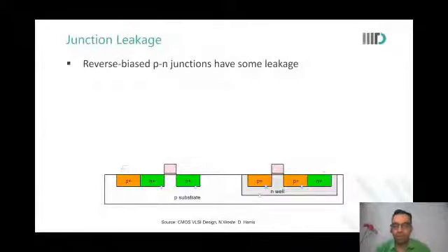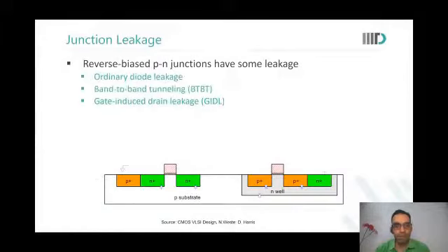Sir? Yes. So you said that to decrease the leakage, we can decrease the body bias basically. But when we are seeing the stack effect, we know that each of my NMOS is in different P wells right now. It's in the same P well.